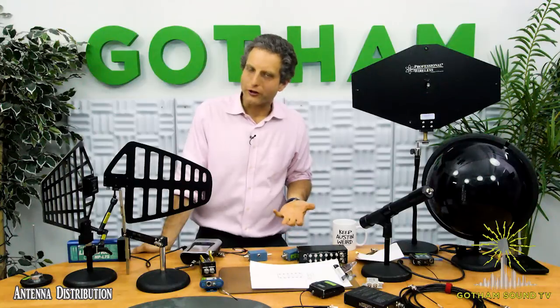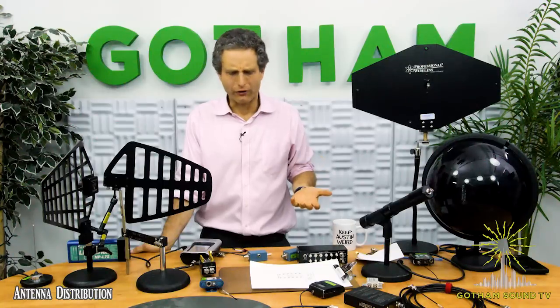And similarly, for example, if you were doing a shot downtown New York, or in any of the major urban areas, or pretty much anywhere where there's a transmitter, if your desired signal was the transmitter, but behind that transmitter was a huge broadcast tower, you might want to orient the antenna in such a way that it rejected the tower but got the desired signal.